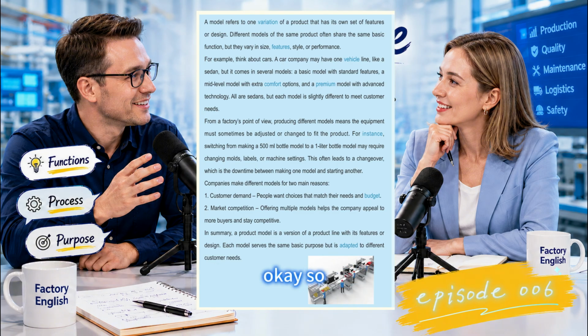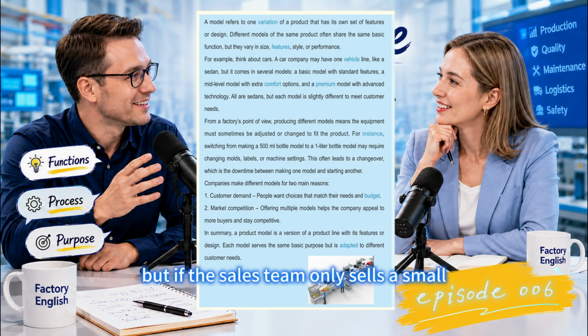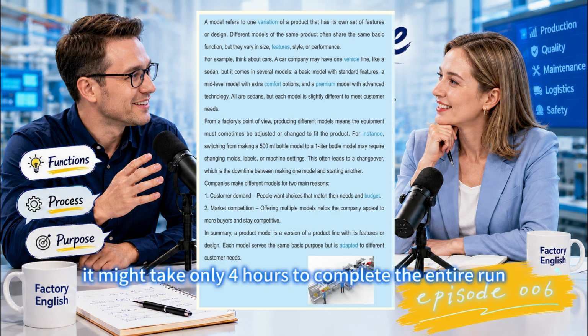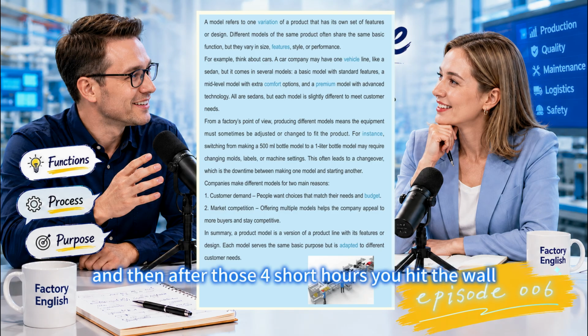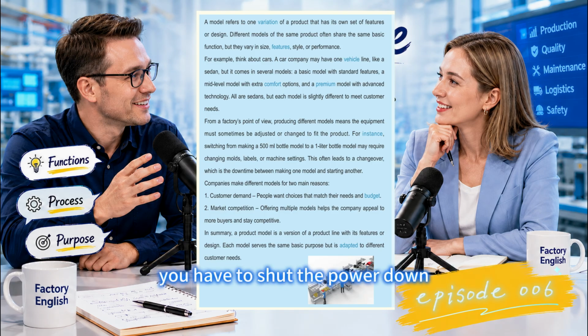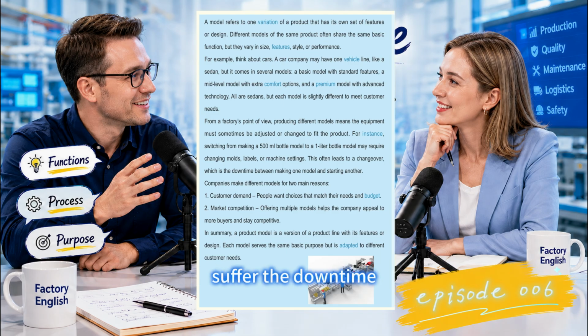So if the sales team secures a massive global order for standard bottles, your batch size is enormous. You might run that single model for 3 weeks straight, enjoying fantastic uptime and high efficiency. But if the sales team only sells a small promotional amount of the premium bottles, your batch size might be tiny. It might take only 4 hours to complete the entire run. Just 4 hours. And then you hit the wall. You have to shut the power down, tear the heavy metal mold out of the machine, do a full changeover, suffer the downtime, and set up the line for the next model.